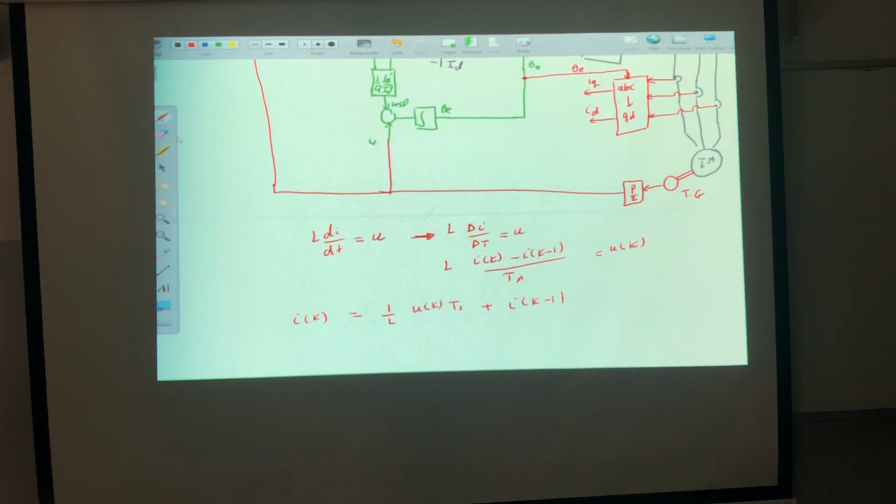So in that time, I did not say that the hysteresis current control will give you voltage. No, it directly gives you gate pulses. But here, the PI control will give you a voltage. This voltage will be compared to a triangular, and the triangular will generate the gate pulse according to whether the reference is higher or lower than the carrier, or the triangular. Anything else?